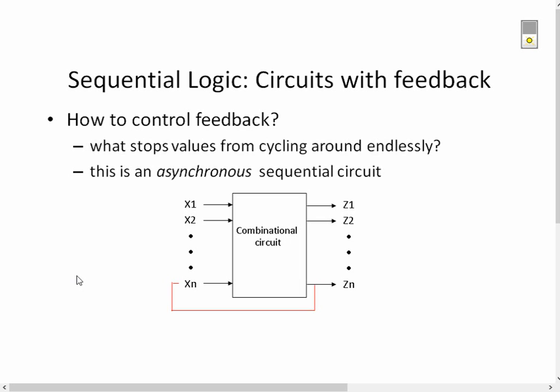And the way that it does that is that I put my circuits together, and those circuits operate much the same way as we've seen before, with the exception that they have this one little feature, which is this feedback loop. I'm going to take the output and put it back in as input. That doesn't create a situation where I just have an input, produce an output, and then it's over. I'm going to hold on to that output because I'm going to push it back in as my input again. So by putting in this kind of feedback loop, I can actually maintain state.